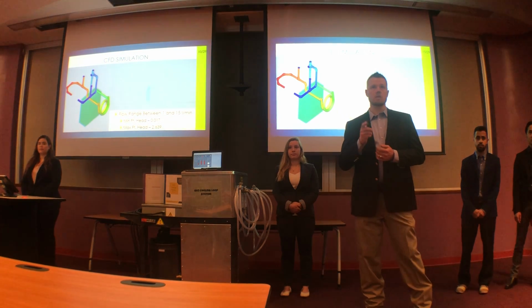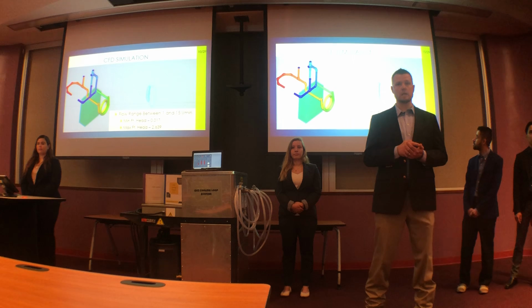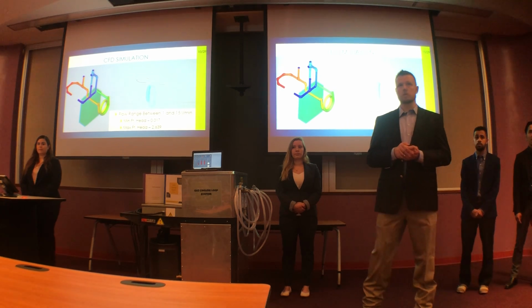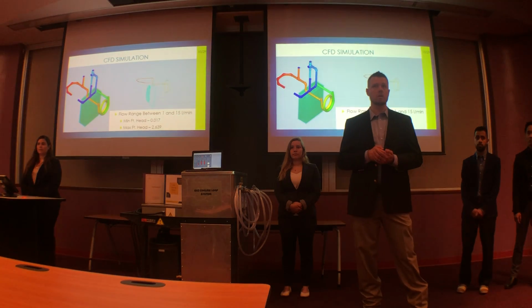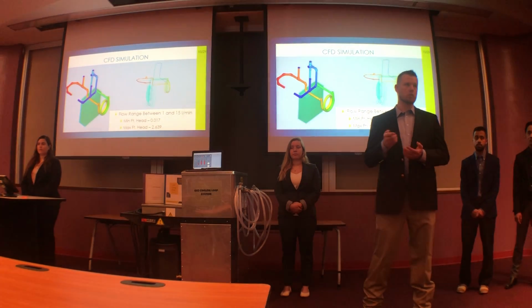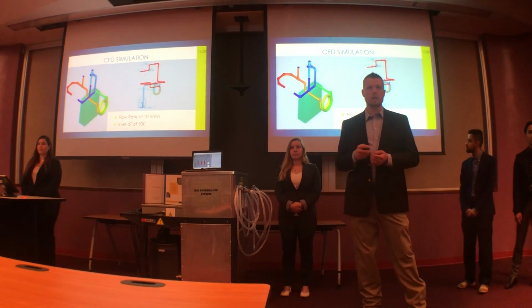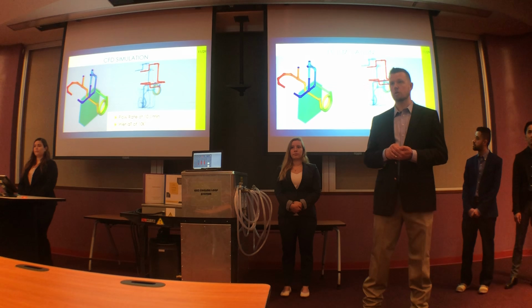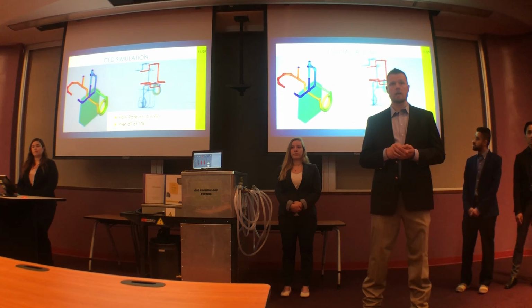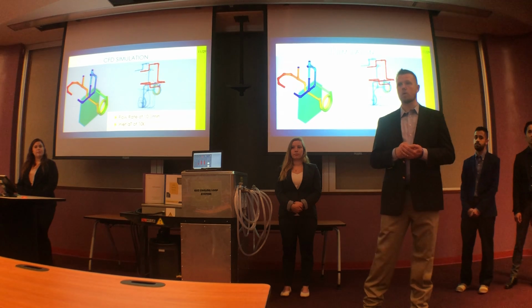On our CFD simulation, we ran it several times between 1 and 15 liters per minute. We saw again a head loss of 0.017 foot and a maximum of a little over 2.6 foot of head loss. On the thermal side, we ran it at 10 liters a minute, and we saw that the system ran stable at a 10 degrees Celsius difference between the inlet and outlet.